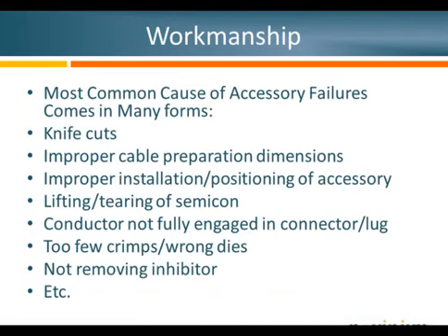And I've seen people overlap the tubes on the termination, and therefore misposition the stress control so that it doesn't land on the end of the cable insulation shield and fails that way. Or they stretch it out way too far and it causes it to miss that way. So proper technique is very important. And you don't want to lift the Semicon, because that creates partial air and partial discharges.